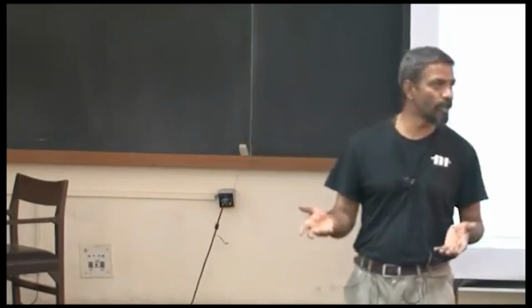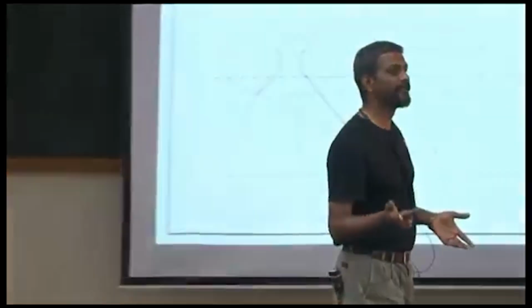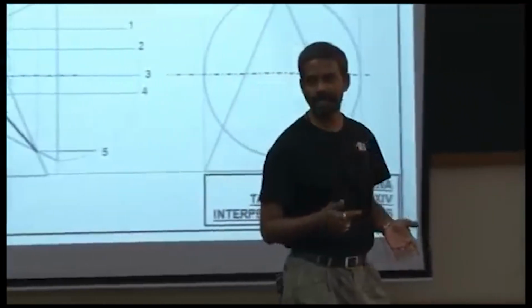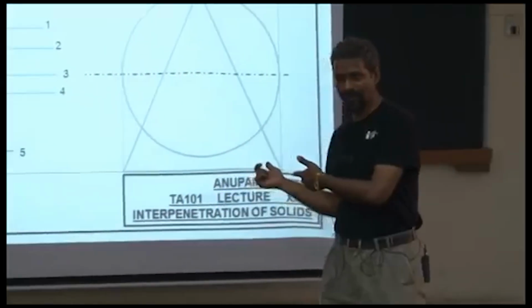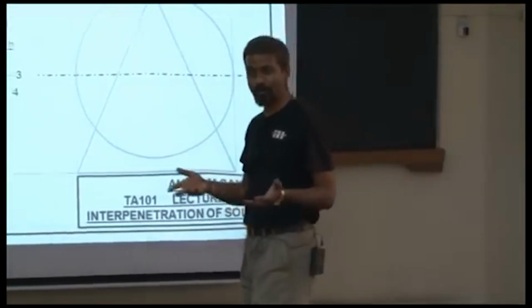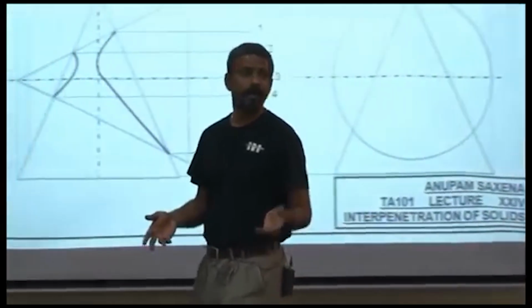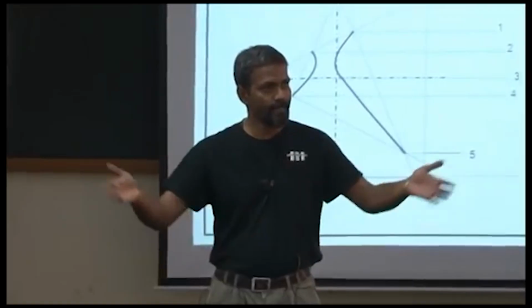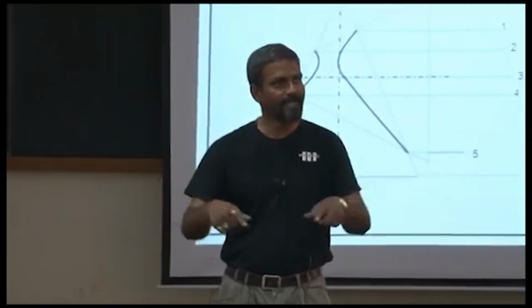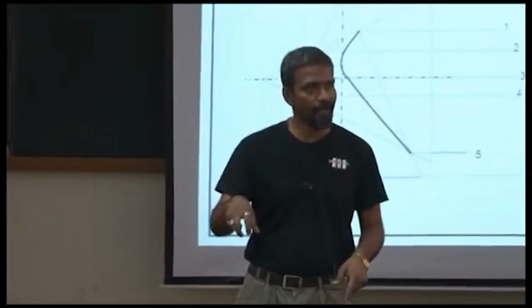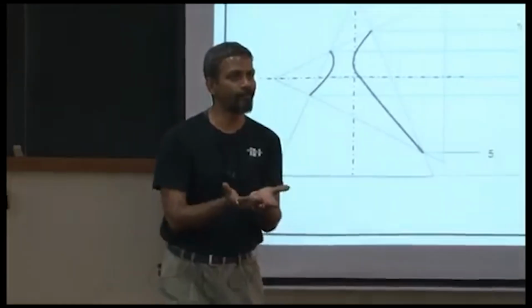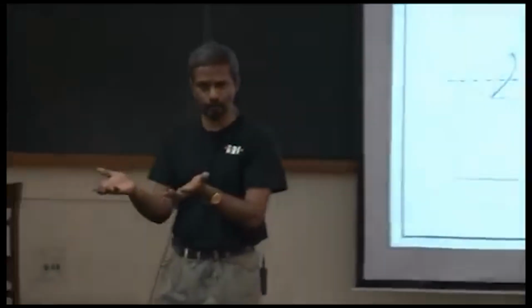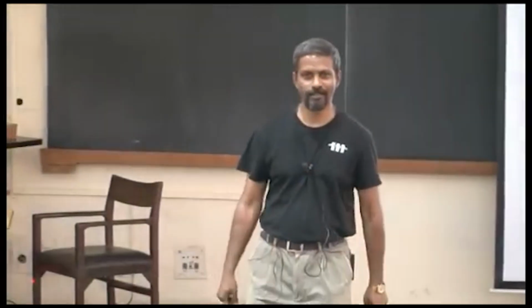And to which I said, well, if you want to learn how to cut it, first you have to figure out the intersection contour between the two solids and use the information that one of the solids is developable. In fact, in the example on Tuesday, both the solids are developable. Use the fact that the cone is developable, cut the cone, spread it out. You already have the intersection contour in there. Cut that part out. Flap or fold your cone back into shape, and then you have the slot.